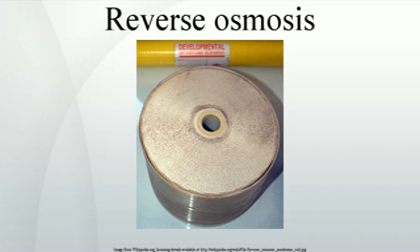Disadvantages. Household reverse osmosis units use a lot of water because they have low back pressure. As a result, they recover only 5 to 15% of the water entering the system. The remainder is discharged as wastewater. Because wastewater carries with it the rejected contaminants, methods to recover this water are not practical for household systems. Wastewater is typically connected to the house drains and will add to the load on the household septic system.